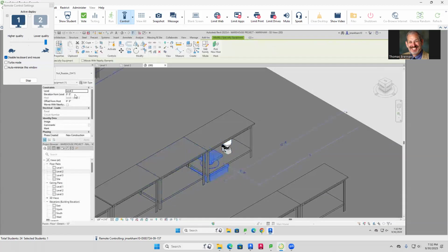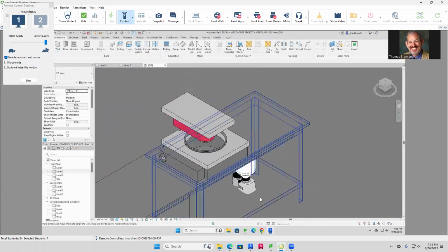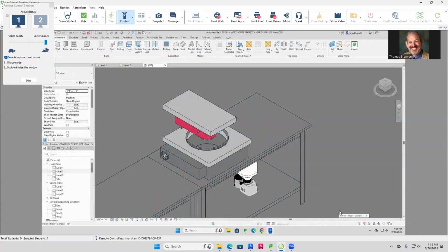So what you have to do is give it an elevation here. It's got to be off the floor. You see where I've clicked over there, the blue. If I make it 3 feet, it brings it right up there. However, if it doesn't quite look right, what I found is that if I use 3 feet 2 inches, 3 space 2, then I can see little feet show up, which works out great.